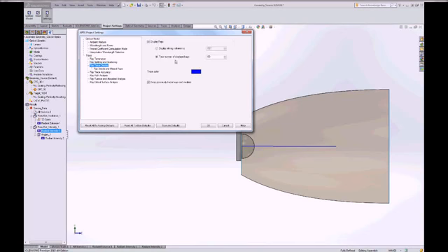But I do want to visualize the rays going through my system, but I don't want to look at 150,000 of them. So I'm just going to have Apex visualize about 100 of my rays. And then because I defined my target to be 100 millimeters away, I'm going to trace the rays 110 millimeters after they stop. So if anything misses the target, I can see it.